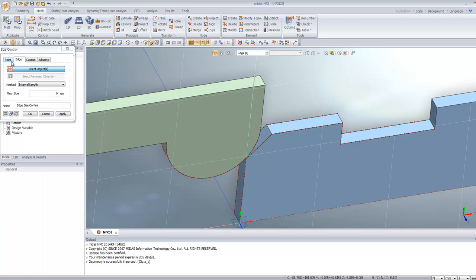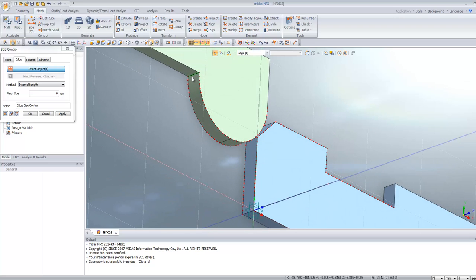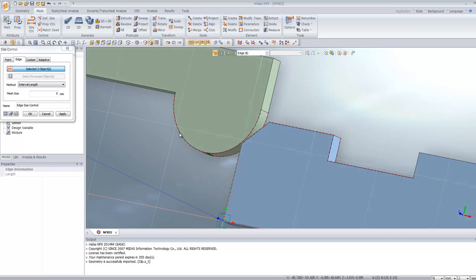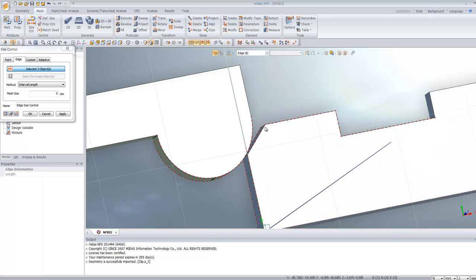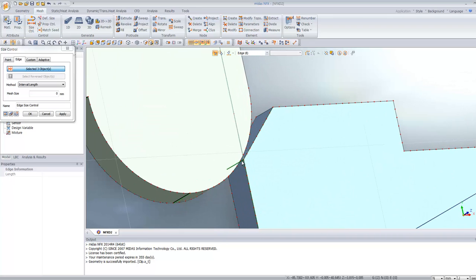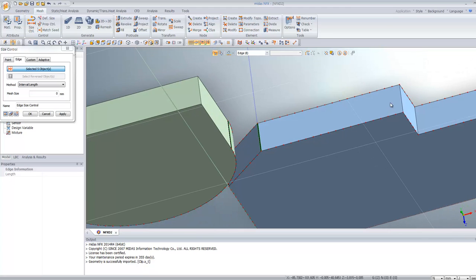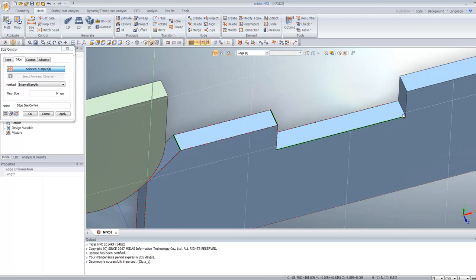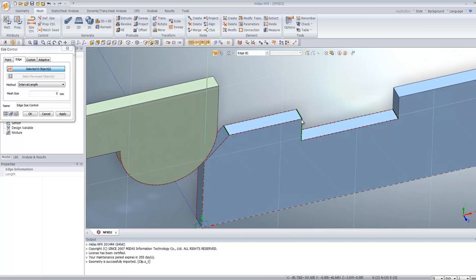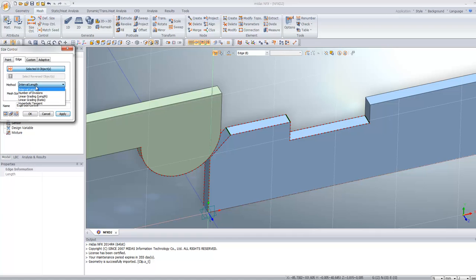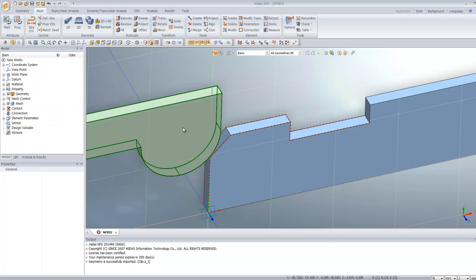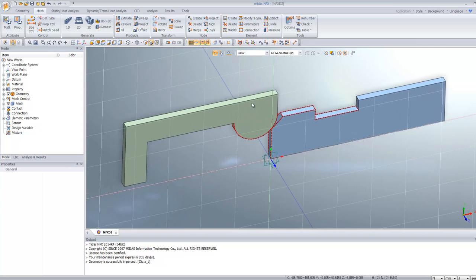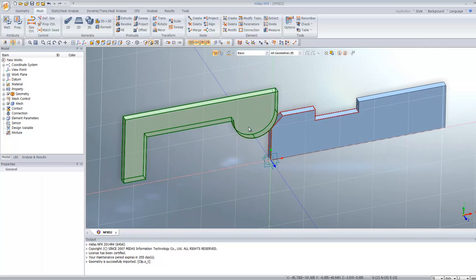So again, I just use this same edge contact, so I select the edges here, so the 3 edges, these edges, this one, this one, this one, and let's say this one, okay. And then I use the number of division, and let's input the minimum 3, let's put okay. So this will help me to control the size on these parts.